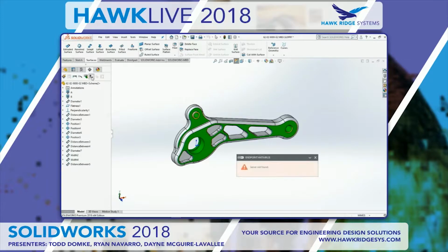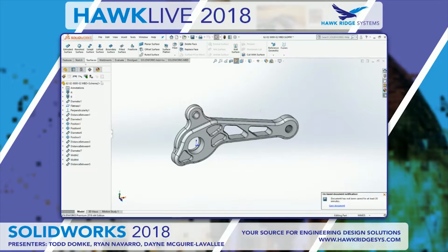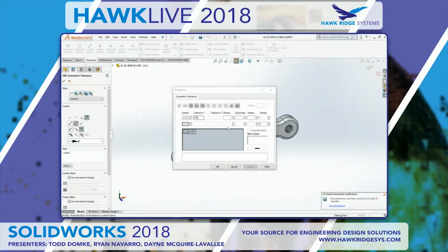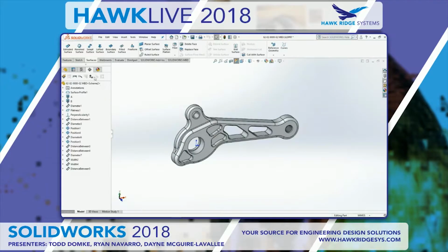One of the great things about ASME code now is it allows a global surface tolerance. So if you ever wanted to just put a global tolerance on there, I can say, just profile of a surface to the CAD model, and then, hey, all of a sudden everything's fully defined, right? Fully toleranced. So it'd be nice if you could do that for all your parts, but now things like that are supported in MBD, and it's a nice tool to aid in dimensioning.